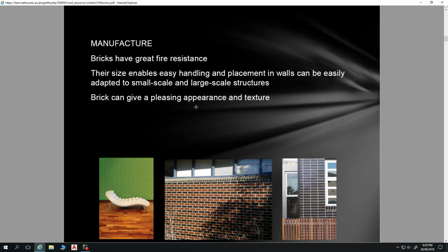Also you've got the concrete bricks as well. Don't have any concrete bricks, but in regards to shrinkage of bricks, clay bricks don't shrink a lot. And when you combine a clay brick with a cement mortar, as that cement mortar goes off, it shrinks slightly, but the brick expands slightly. So you don't get a lot of expansion or contraction when you're laying a fresh brick wall.